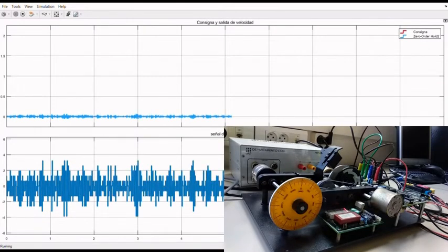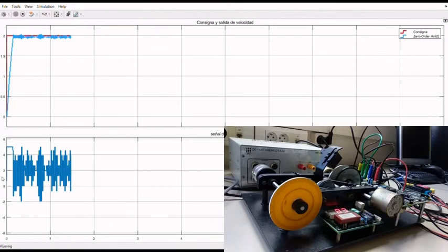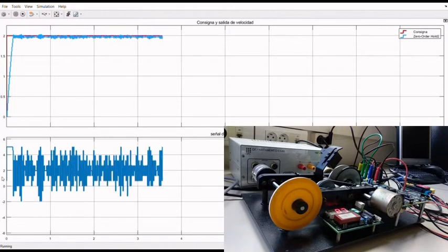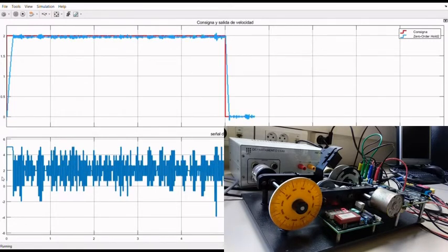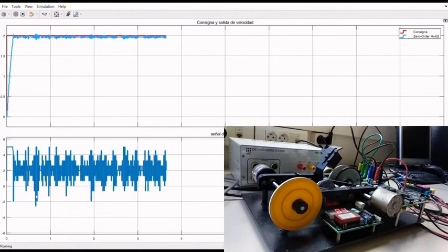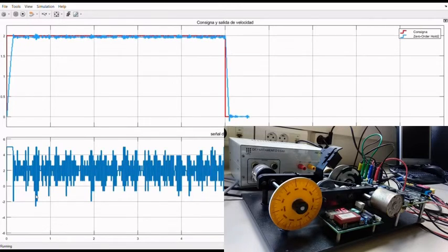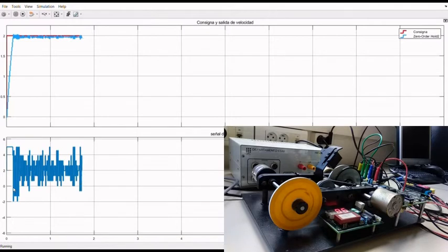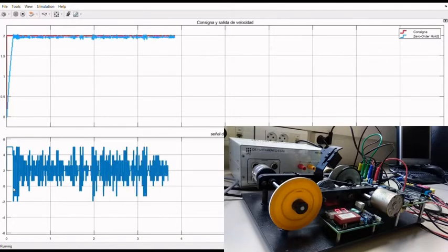In this video, the closed-loop experimental behavior can be observed. As we can see, the motor has a constant velocity when applying different references instead of getting unstable as seen in the simulation. This comes from the fact that the control signal has limitations. The control signal is limited to 5 and -5 volts, so the motor cannot take higher velocities. Due to the high gain in the proportional controller, the control action switches between different values.